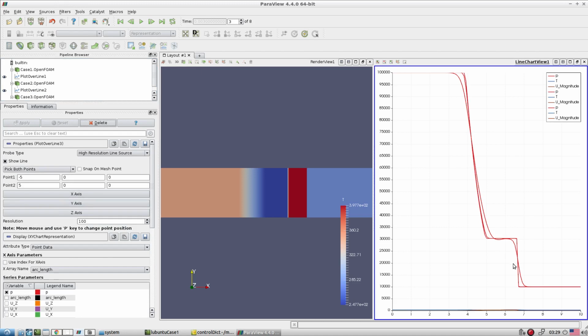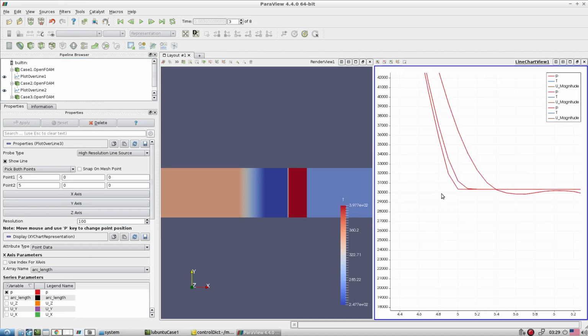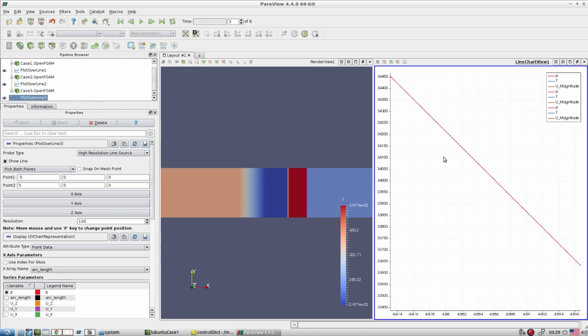So look, when we go from here to here, you will see a very small change appears. That means we are almost going towards grid independency. Further we refine the mesh, we hardly see much more difference in this area. This is how one can check; it is hardly changing. Here in this case, the sharp corner doesn't resolve, but here we are able to resolve the sharp corner.